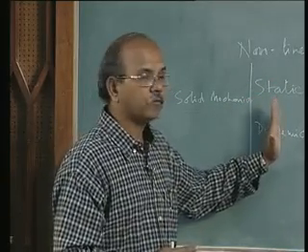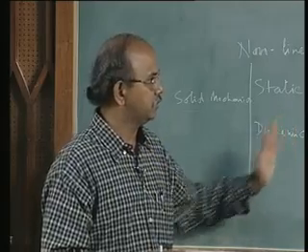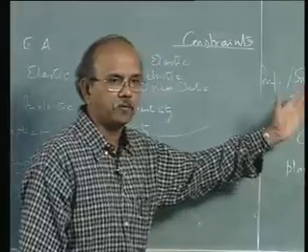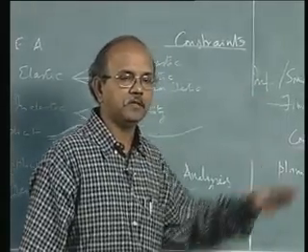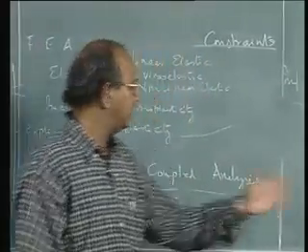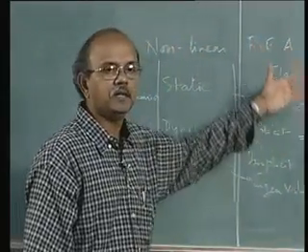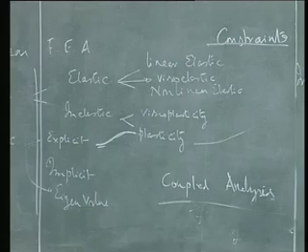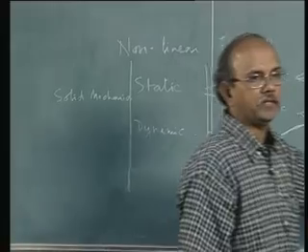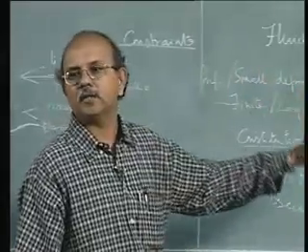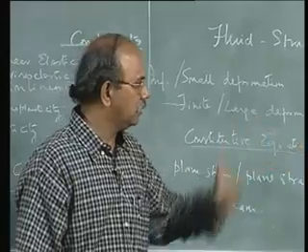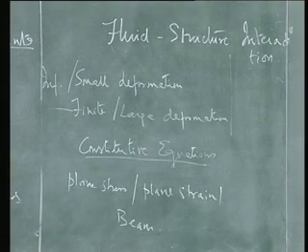So once you decide what is the type of analysis you are interested in, you also have to look at whether the problem is going to be a small deformation problem or a large or finite deformation problem. That's the next thing that you will decide. Then afterwards you will decide what is the material property that you will use. Of course, along with it you will choose the type of element that you will be employing in order to solve that problem, whether you are going to use a shell or a membrane or a solid element and so on.